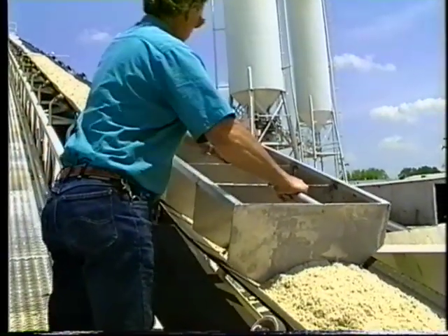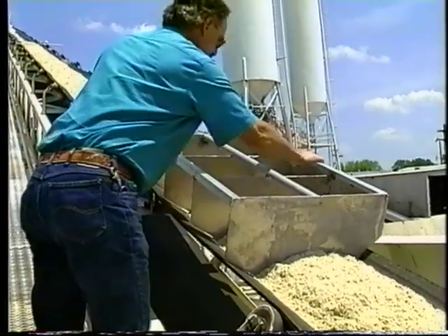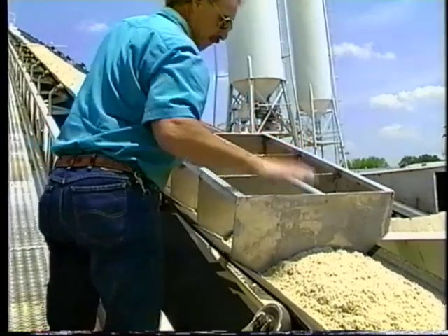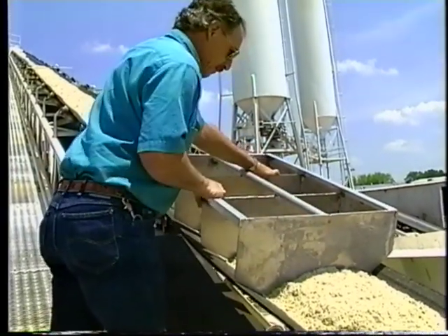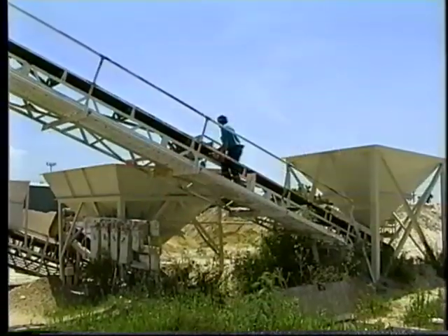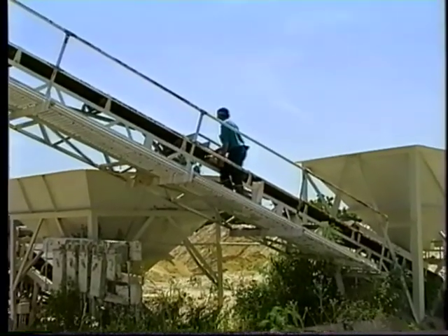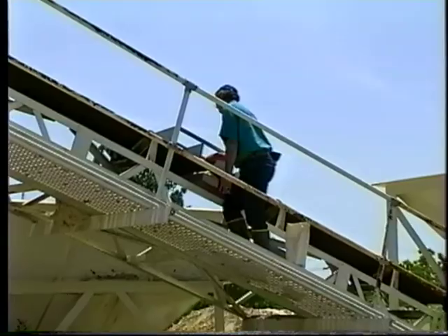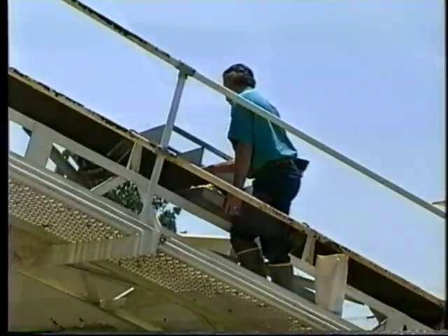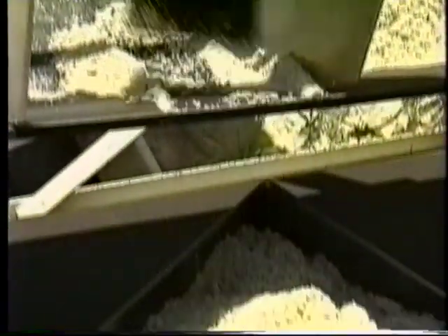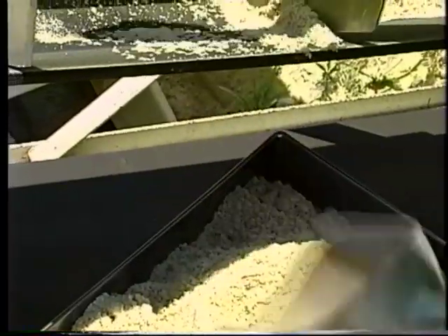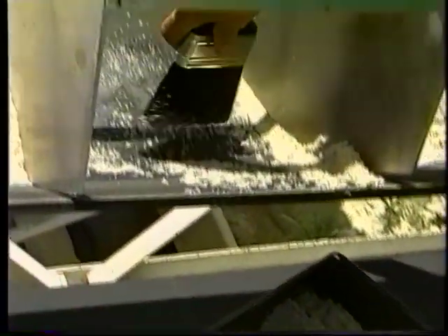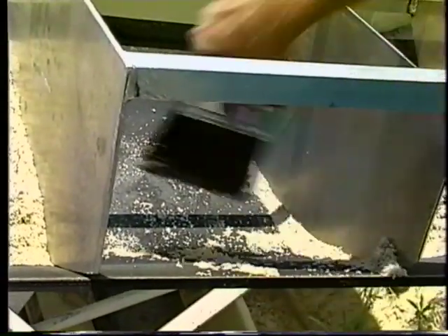Use a template of proper length and cross-section to obtain the representative sample of proper size. The template must be designed to conform to the shape of the belt being sampled. Using an incorrect template will result in a sample that is the wrong size or not representative of the material. When removing the sample from the belt, be sure to capture all fines. Failure to do so will result in a sample that is not representative of the material.